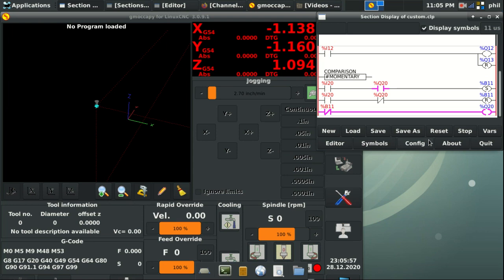So getting into it, what I'm going to do is tie in my trusty PlayStation controller to utilize one of the buttons to control input number 20. Now input number 20 is going to pass through this circuit and the circuit right below it. There are a normal open and normal closed, or make and break, coil tied to each of the rungs. The B11 set and reset tied to a B11 break input down at the bottom, and that passes along to output number 20.